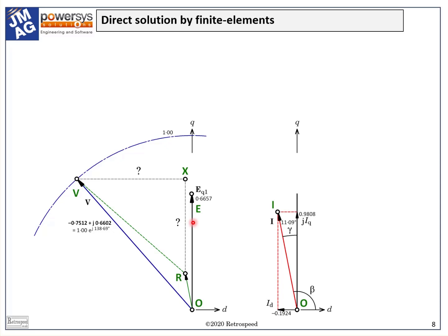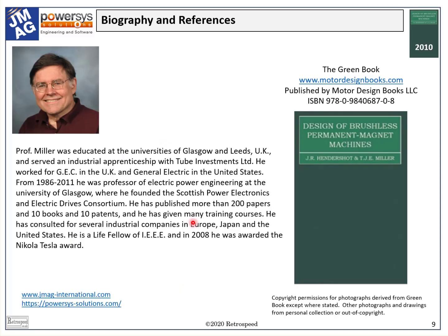Turning aside from these considerations, the question also arises, of course, as to whether there is a maximum speed. There will certainly be a maximum permissible mechanical speed determined by the physical strength of the rotating components and their bearings and dynamics, among other things. There will also be diminishing torque. Ultimately, the best that can be hoped for is to maintain constant power equal to the limit available from the inverter. What happens at high speed is rather a fascinating subject, and it is quite complicated.